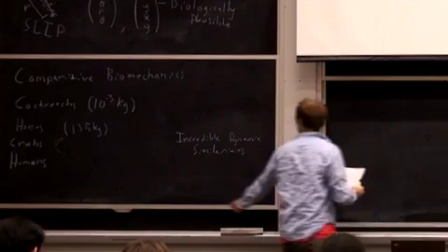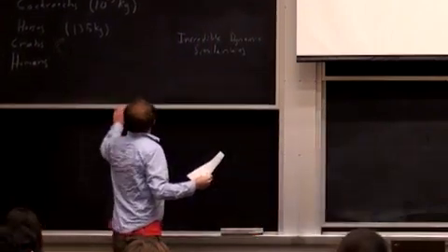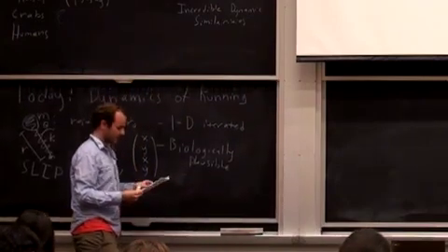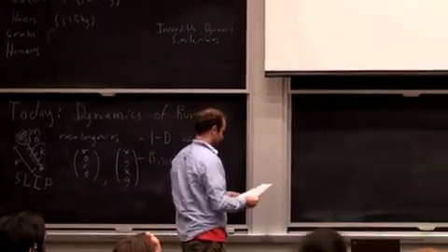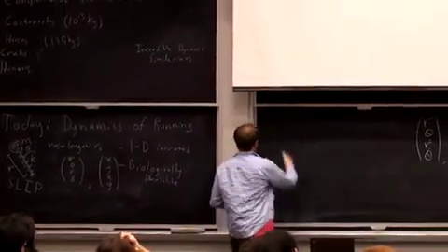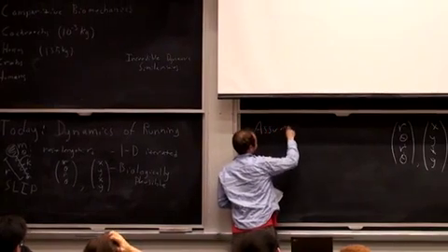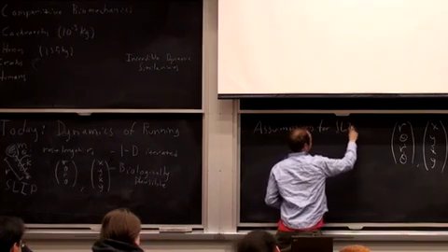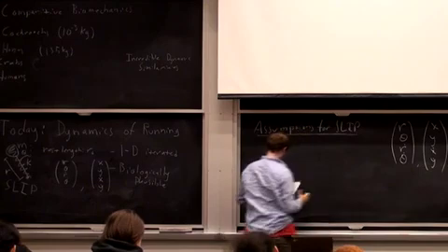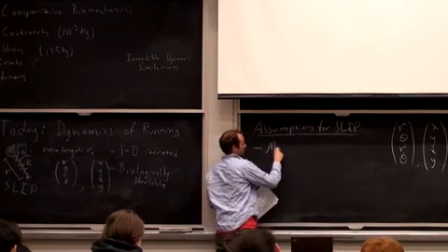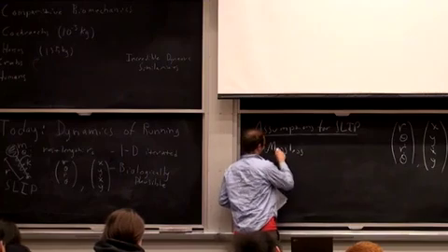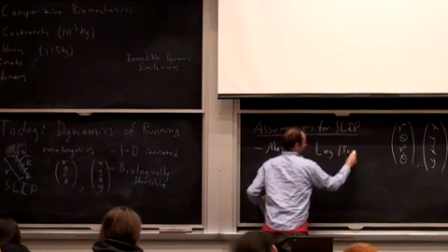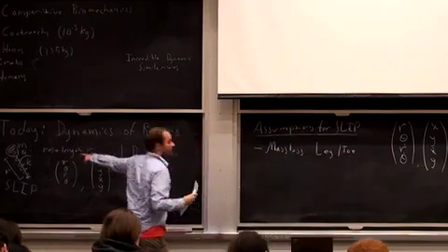All right, I'll bring this one back down. And let me put in the assumptions really clearly of what this model is going to have. So the assumptions for the SLIP model. One is that you have a massless leg and toe. All right, so all your mass is concentrated in that point mass that is the body.